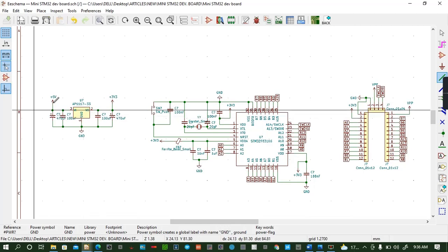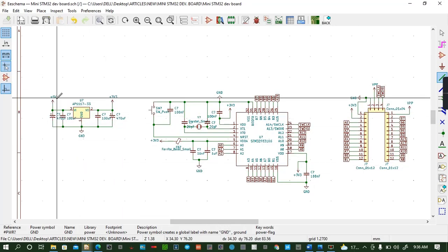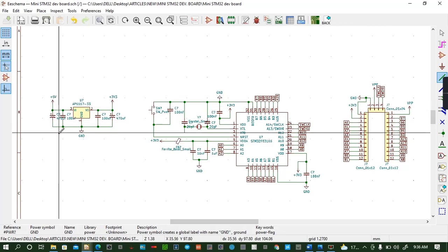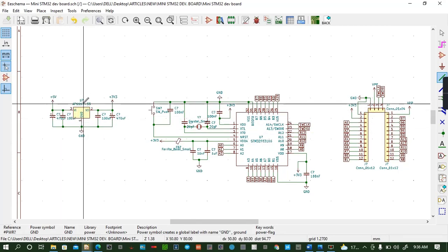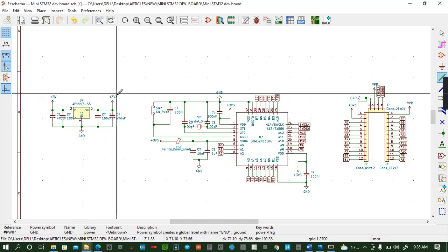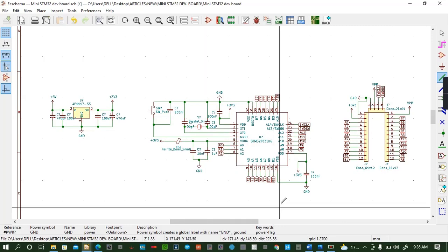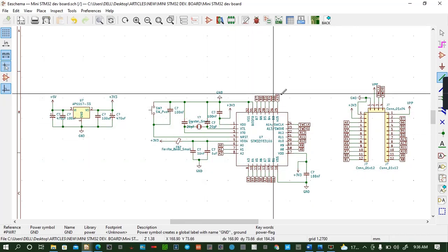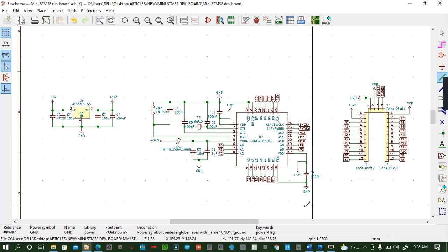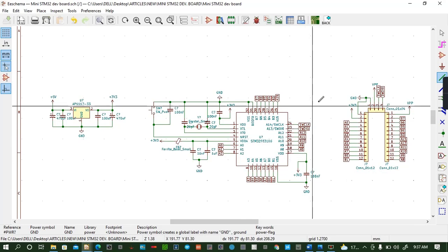It works like that. We have the power supply system here, 5 volts. This one you will be powering using your laptop. You power your board, and then we have a voltage regulator here, which will regulate the voltage to 3.3 volts, which will be the output that will come and power this board here. You can see here we have 3 volts that are required here to power this system, the STM32F031K6.